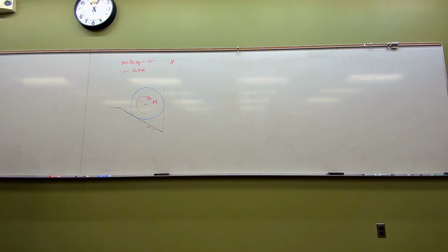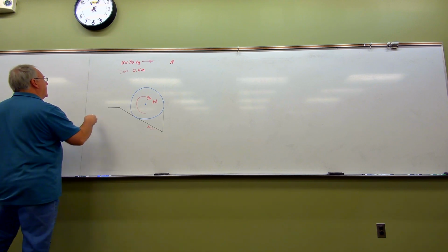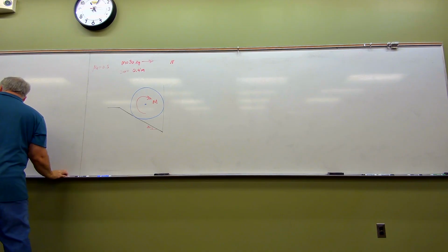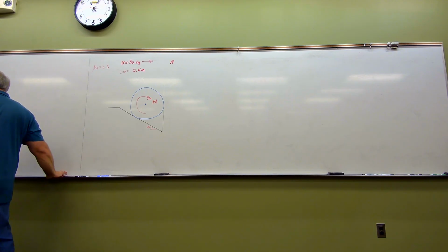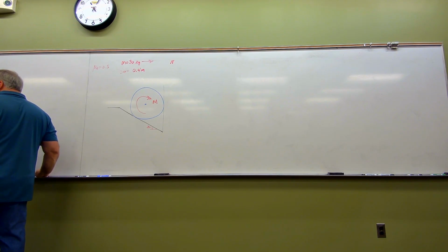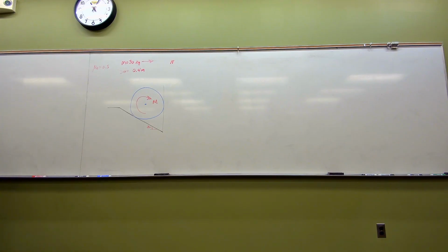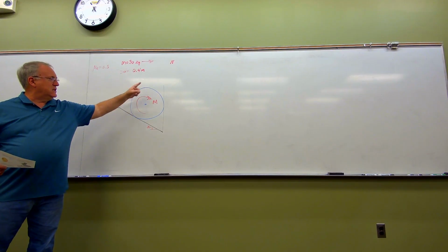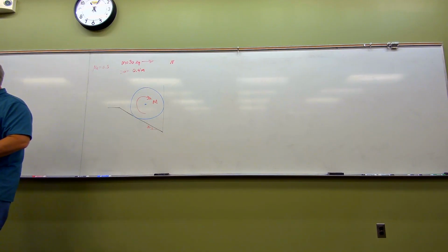If the coefficient of static friction between the cylinder and the surfaces is 0.3. So once again, we have the same mu sub s as we had before. Mu sub s is equal to 0.3. Calculate the applied clockwise couple M, or moment M, which would cause the cylinder to slip. We just simply want to know how much moment, how much torque would you have to apply to the cylinder here to get it to actually slip within this V-shaped thing that's holding it.